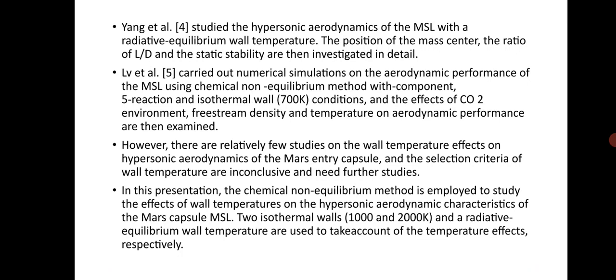Lv et al. carried out numerical simulation on the aerodynamic performance of the MSL using the chemical non-equilibrium method with 5 components and reactions and isothermal wall of 700 Kelvin conditions, and the effects of CO2 environment, free stream density and temperature on aerodynamic performance are then examined. However, there are relatively few studies on the wall temperature effects on hypersonic aerodynamics of the Mars entry capsule, and the selection criteria of wall temperature are inconclusive and need further studies.